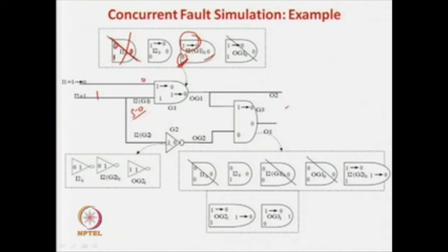So, you can find out that for the ordinary gate the signal was 1 0 1 0. So, in this case it is 0 0 and the answer is a 0. So, again by the same logic as I2 stuck at 0, this gate is also retained, but this computation and this computation are saved. Now, let us look at the output of the gate, which is changed.